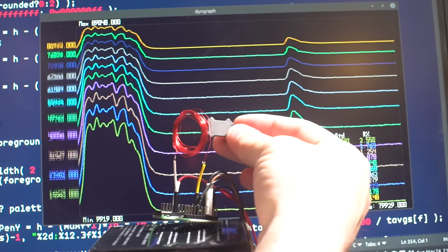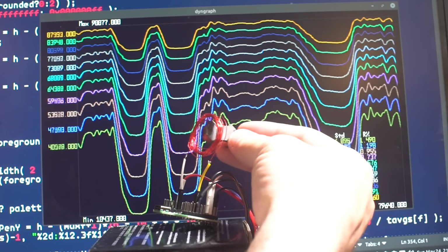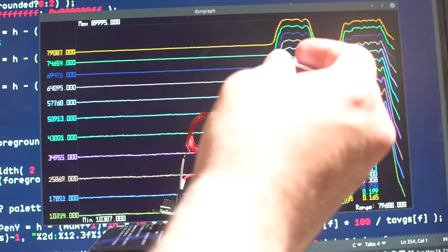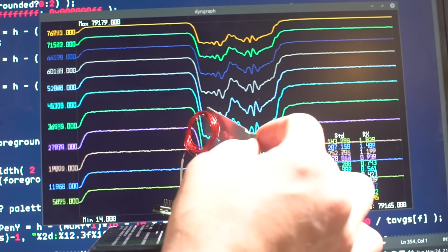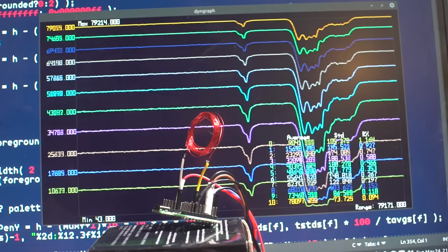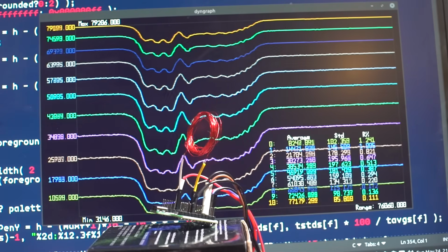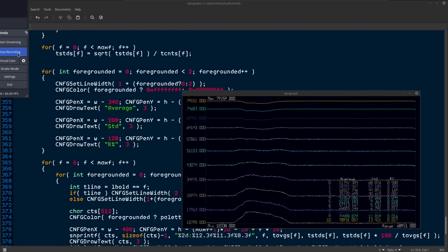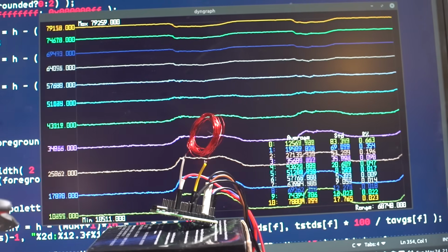If I take a piece of transformer ferrite for a high-frequency transformer, we can see that it greatly increases the inductance. But if we take something like aluminum from an aluminum circuit board, it reduces the inductance of the system. There are lots of other materials that have other interesting properties. You can see most of the metals in here will reduce it. But there are other materials, like this pair of clips here. For some reason, interestingly, it causes the waveforms to actually pinch together.